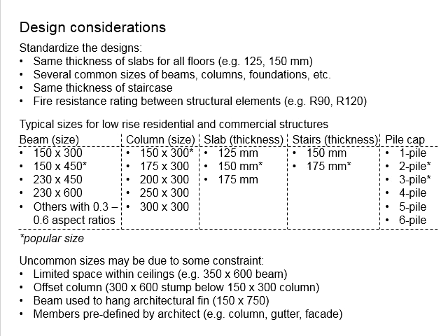That means the strategy of the designer now is to use the materials to compensate for the tediousness in the fabrication of the beam. And the quality of casting is also better because you have plenty of space in the slab as compared to the narrow space between the reinforcement bars in the beam.